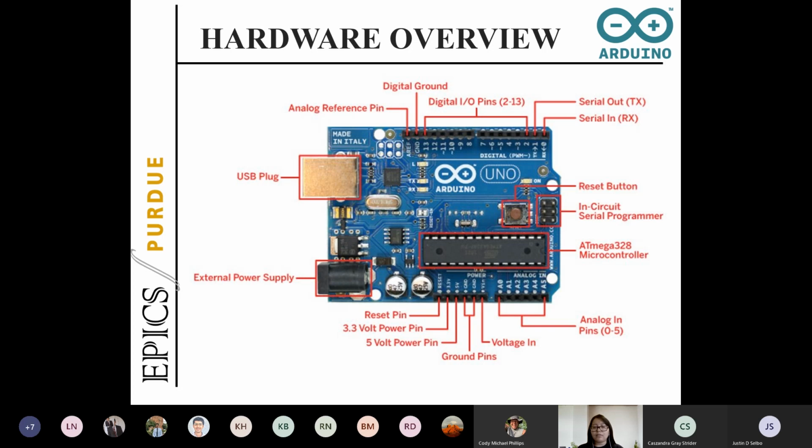And then on the other side, we have this power voltages pin that can supply 3.3 volt or 5 volt power, and it depends on the project that you're using. So you can energize any external electrical components with these 3.3 volts or 5 volts. You can connect directly from here, so it will function as a regulator, sending you this voltage constantly. We do have ground pins again.